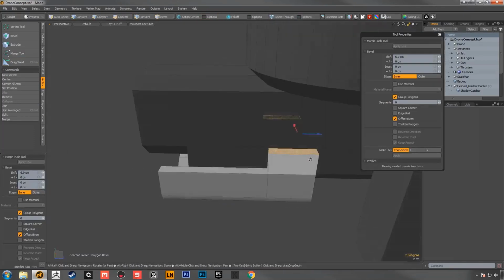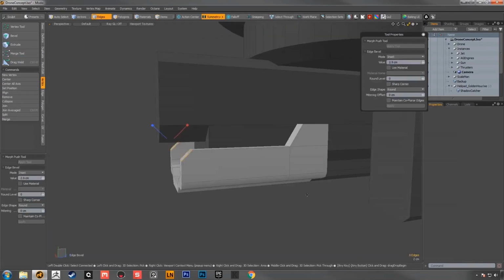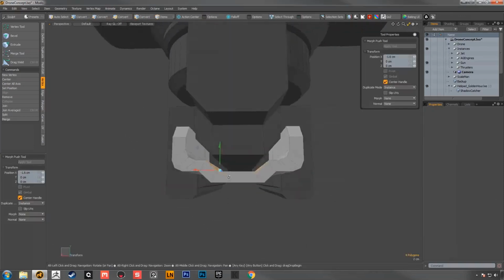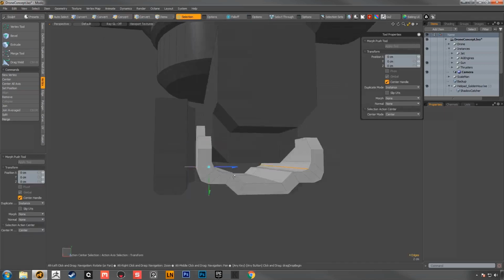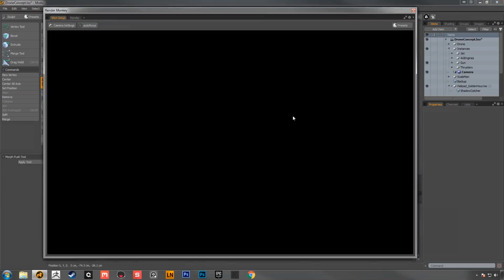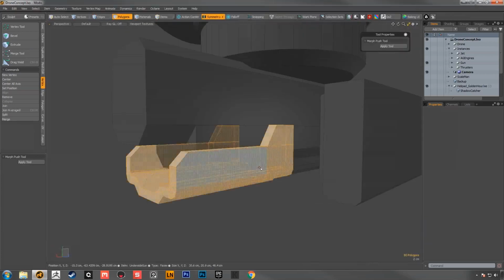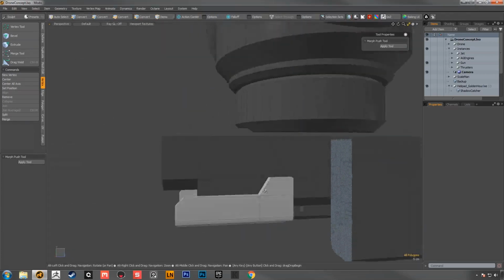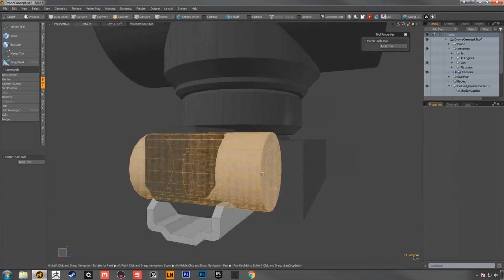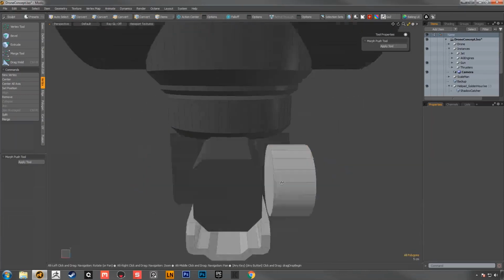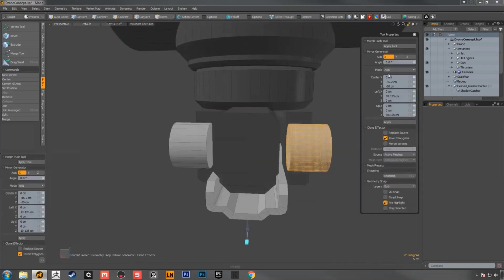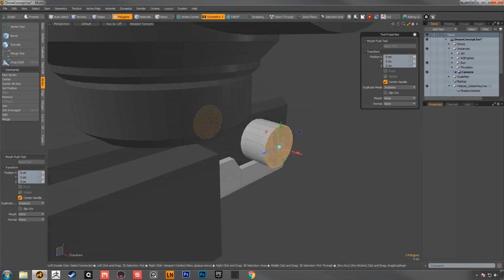And if later on a tech artist comes to me and says that this is just too high poly, then we can go into the mid-poly modeling and start to figure out how we could reduce the bevels or reduce the overall complexity of the mid-poly modeling. And because of the whole process, it's very easy to re-UV and reapply the materials within minutes, instead of needing to start the entire process of rebaking a high poly to a low poly again.